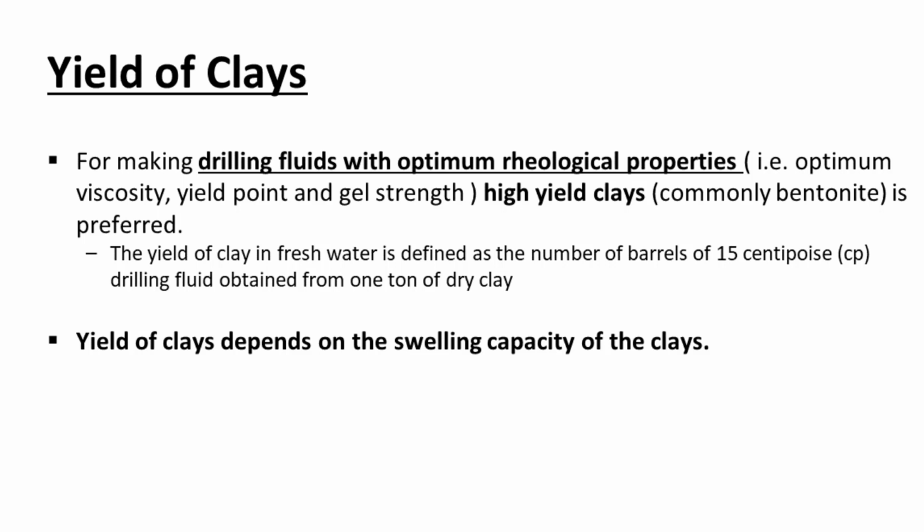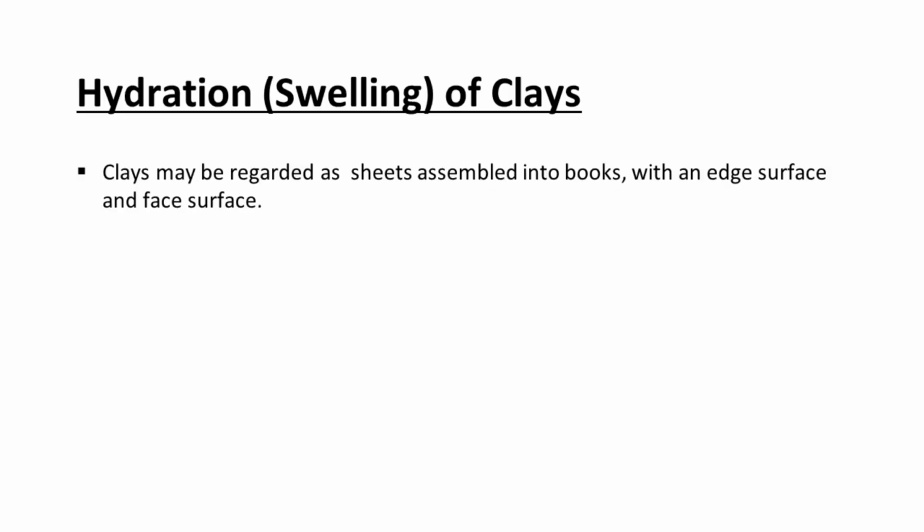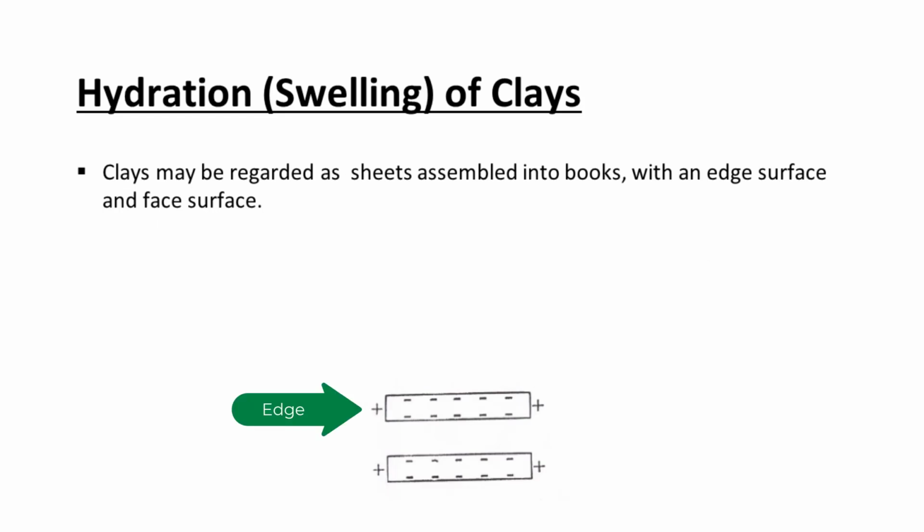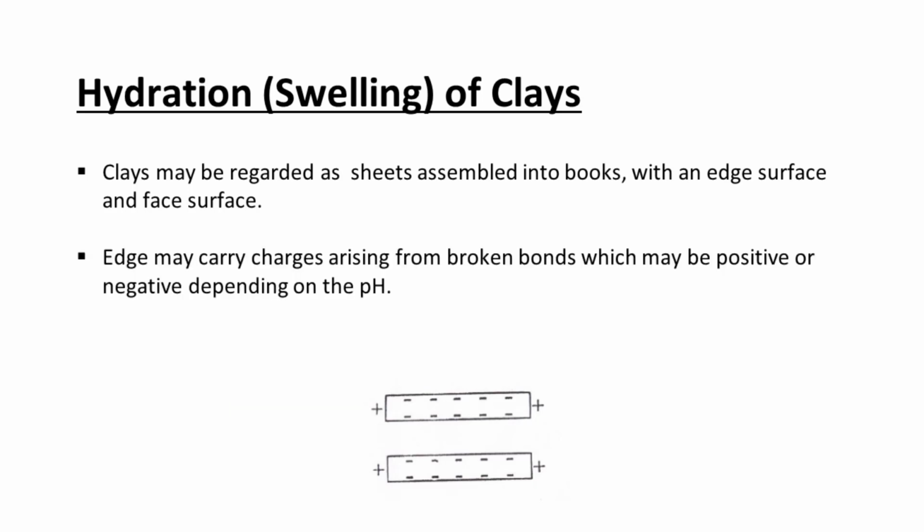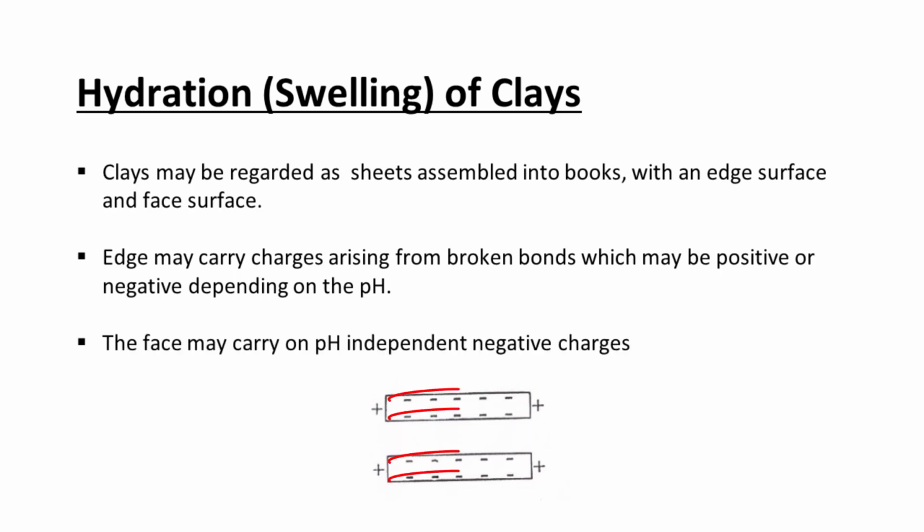Hence, it is important for us to understand the factors associated with the swelling of clays. Clays can be seen as a stack of thin sheets of molecules, with each sheet having an edge surface and a face surface. The edge of the sheet may carry charges from the breaking of bonds, and the charges may be positive or negative depending on the pH. On the other hand, the face of the sheets will always carry negative charges.